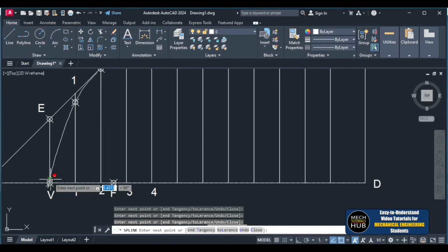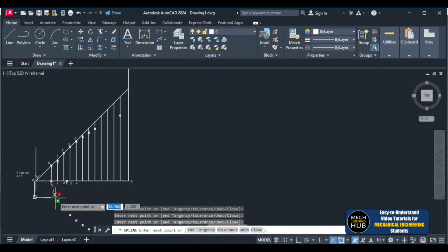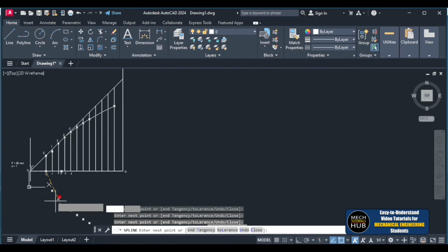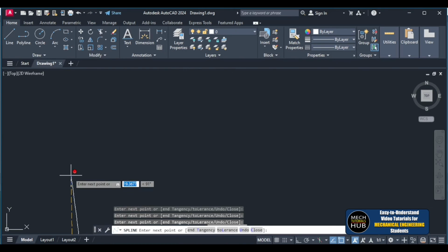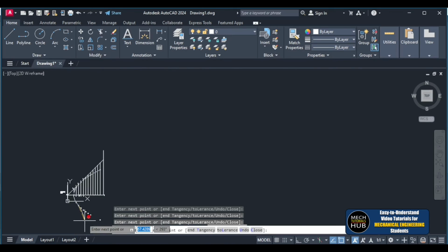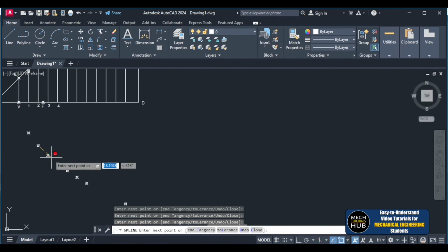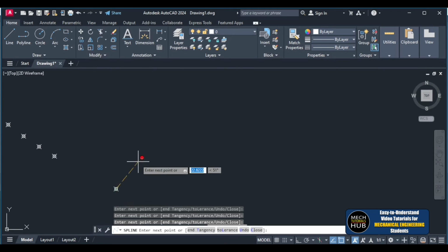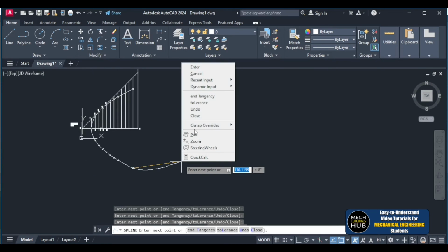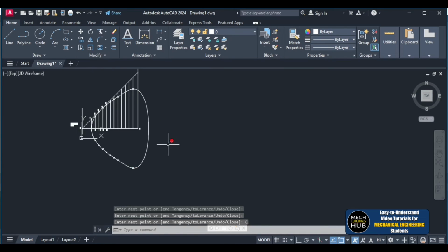So now it will start the curve, whether it is an ellipse, parabola or hyperbola. It is going to start at the vertex point. So here it is meeting. This is the next point, next one. Or else you can copy, no need to select also. You directly copy and mirror it. Other curve you can draw, or on the other side you can simply mirror the curve. Now if I click on close, this is how it is going to be.